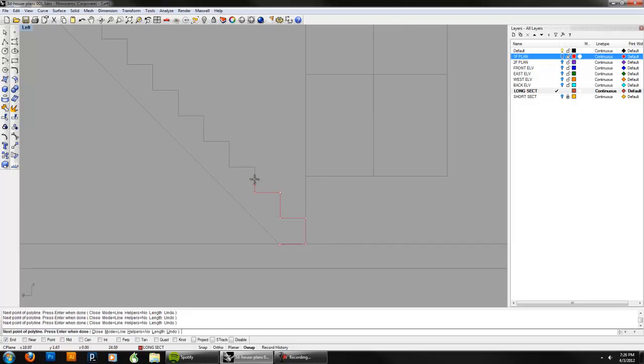It's very hard when you're modeling in AutoCAD, or when you're drawing in AutoCAD, to really guarantee that all of your lines are really closed, that they're grouped together, let's say. And so when you export them and when you extrude them, you don't always get the result you want. And so by tracing over them in Rhino with the line tools and by making sure that they're closed, you're going to get a really nice surface when you're done with it.